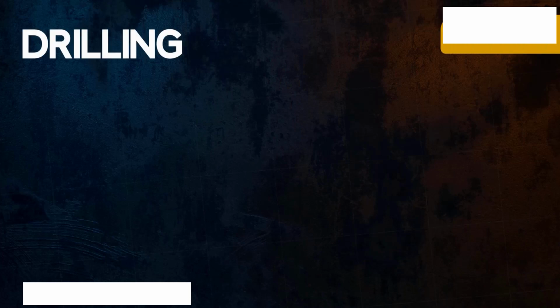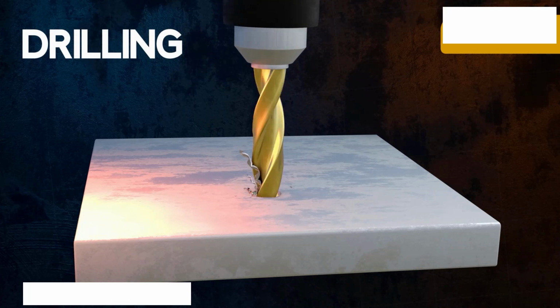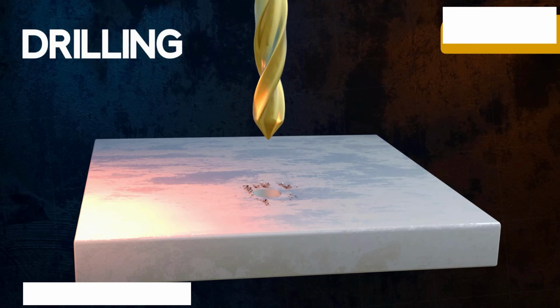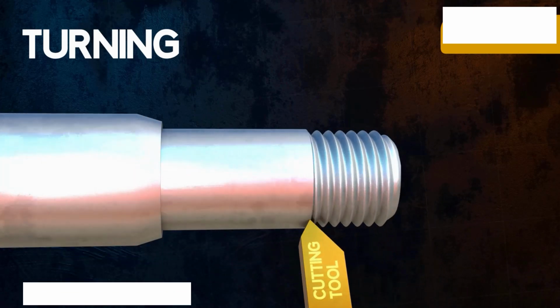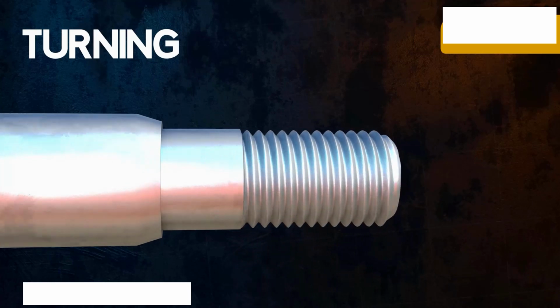Machining is a process in which there will be a controlled removal of material from a part to create a specific shape or surface finish. There are different types of processes, such as turning, milling, drilling, broaching, and shaping. This is also called a subtractive manufacturing process. A sharp edge cutting element is used to remove material. There should be a relative movement between the part and cutting element in order to make this process happen.